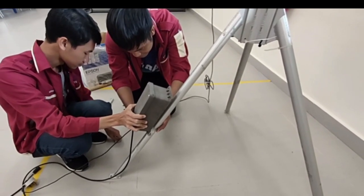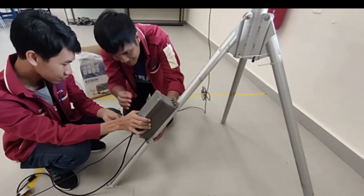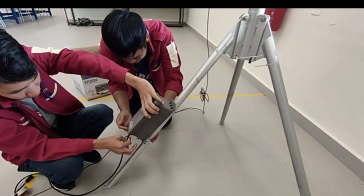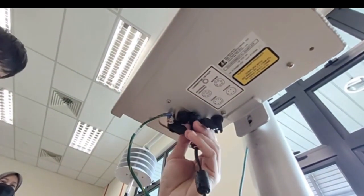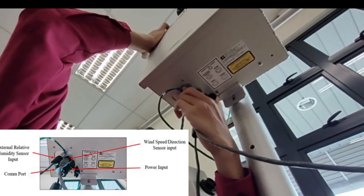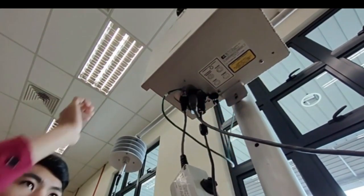The power supply was plugged into the main power connection on the bottom of the E-sampler. The power supply was attached at the bottom of the E-sampler unit and was tightened with nuts. The external input from the relative humidity sensor and wind direction input were also plugged into the appropriate connectors on the bottom of the E-sampler. Lastly, the COM port input was connected from a personal computer for data storage.